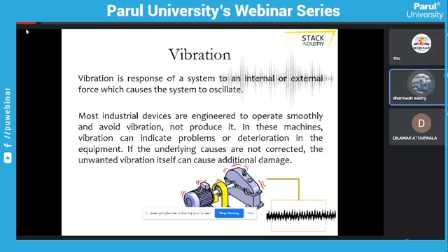Sometimes in a running motor, if a fault occurs, the first thing that happens is it will start vibrating a little bit. It might be damaged due to internal or external forces. For example, in a company there are many types of motors, centrifugal pumps, and gearboxes. After some age or time, or due to misalignment or some other reason, if any fault is there, it will start vibrating.